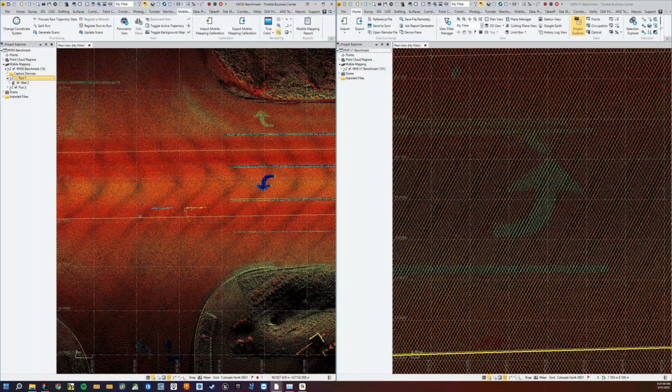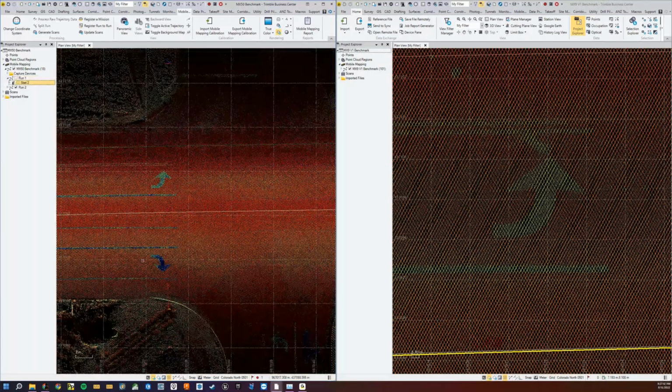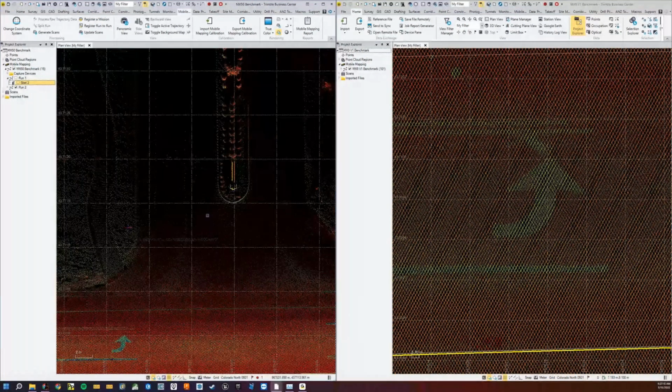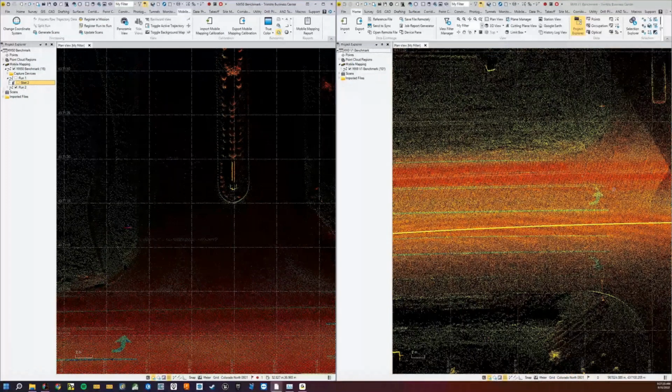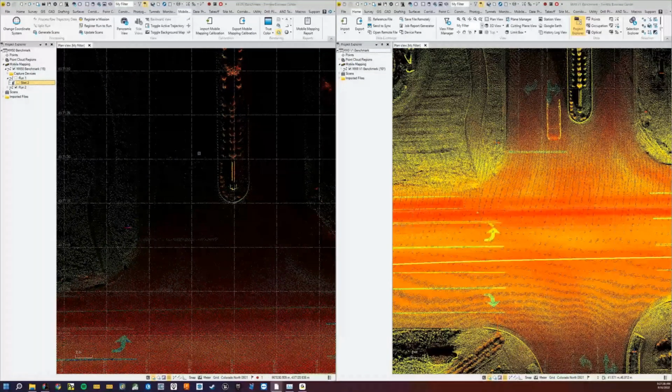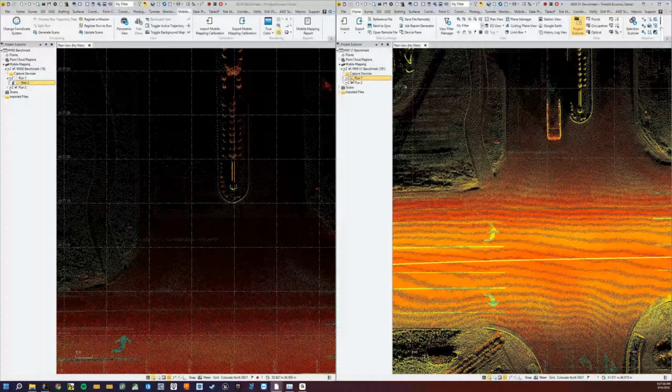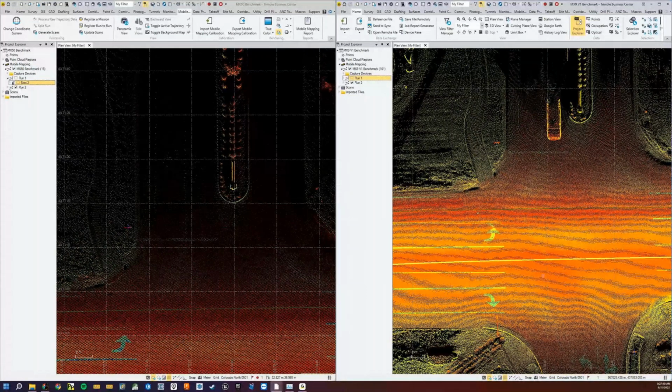So what I just had is still pretty sufficient for everything on your side of the road, and everything in the other lanes. When you get to this turn arrow right here, that's where you have that border of things starting to fall off, might not be extractable, so we'll do that same thing here. You can see the turn arrows that we're looking at there, a little extra density. Let's turn off the first run. So you can see we retain a few extra points, a little more definition on those turn arrows. There was a car here, so that took away some of that. But that shows a little bit of the difference in range. These are both at their higher rate.